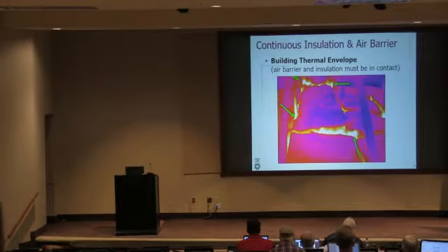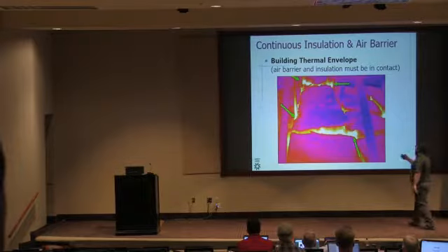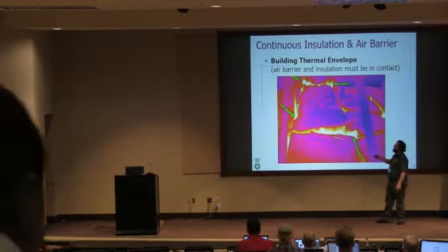All right. Real quick, sort of a review of building science, because when I say the house as a system is a building science-based approach, this is what Southface's world is based on. These concepts of how do houses deal with the transfer of heat, air, and moisture, and what is the science behind it. So we say you've got to have a complete, continuous thermal boundary, an insulation and air barrier.